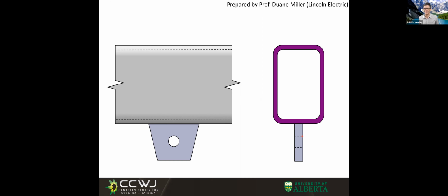Aha, some say good, some say bad. No, this is bad. This is bad because we're welding against a compliant section, right? This horizontal part is like a membrane. We can put our weld there, and we put a load that is going to be resisted how? On the vertical sides, on the parallel sides of the load.